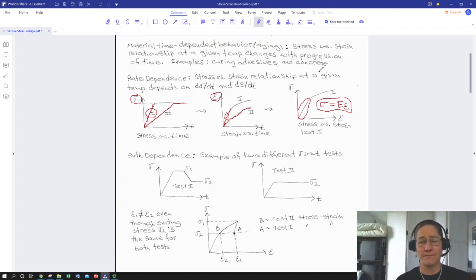For most engineering materials, at least most metals, this is very small compared to the other portion where stress is not proportional to strain. Now, something really important happens here that we'll discuss more. This point where the stress versus strain curve kind of heels over, and we get a lot less stress for every additional increment of enforced strain in the material.